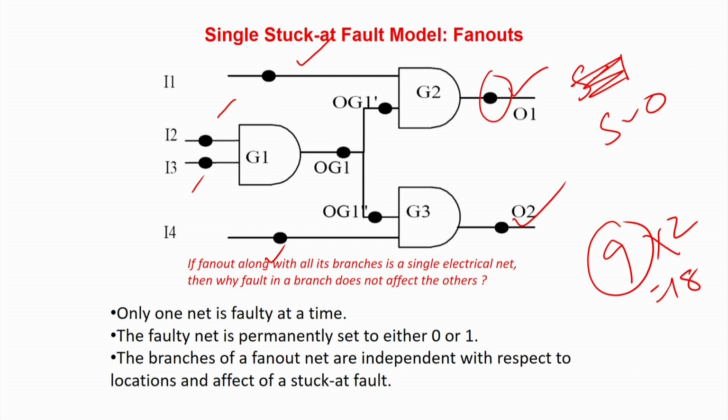One byproduct that has been found for the stuck-at fault model is that if there are n lines, of course there are 2n faults, because of stuck-at 0 and stuck-at 1. But 2n patterns are not required. The number of patterns is much lower, because one pattern can test multiple faults. So in this case we will not require 18, we will require much less than that.